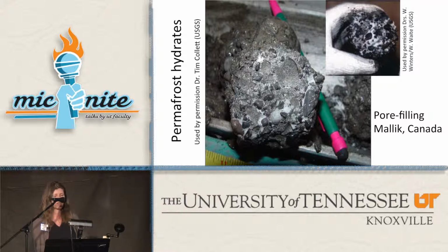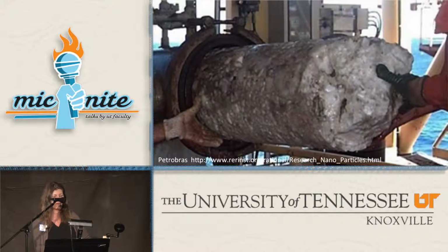The conditions for hydrate formation are often found in gas pipelines, resulting in pipeline plugs that can reduce flow or cause pipeline damage when a large amount of pressure builds behind the plug and the plug blows. The gas and oil industry find these pipeline plugs highly undesirable, and flow assurance engineers work to prevent these plugs from occurring in the first place.